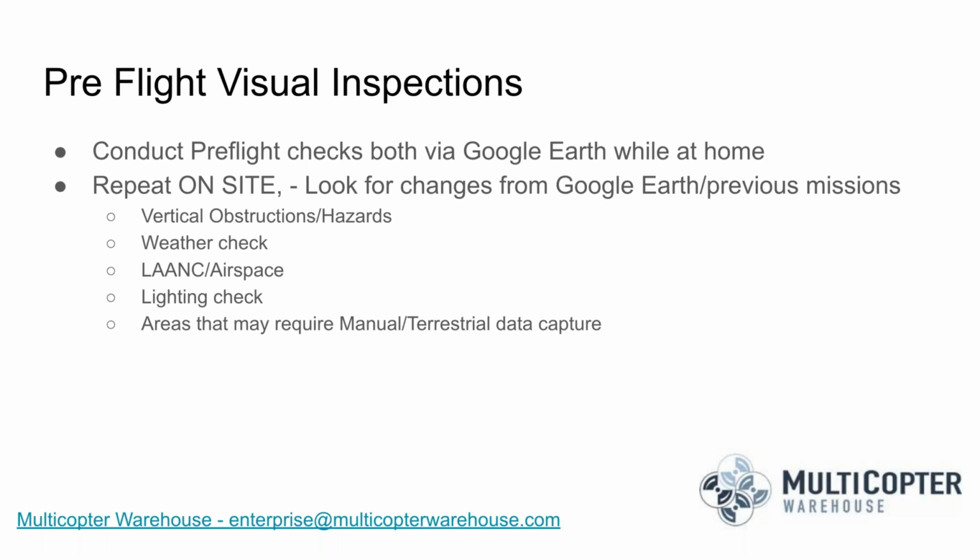Let's see. How would you use a P4 Pro for agricultural mapping? Well, that actually goes a couple different directions. You can do it for mapping the field and getting altitudes and some crop heights and things like that, but you're not going to get NDVI data or multispectral data that will show you the health of the plant or the nitrogen level or things of that nature.